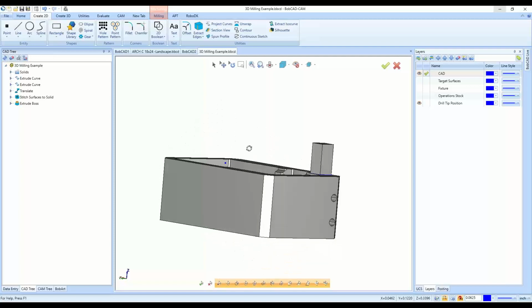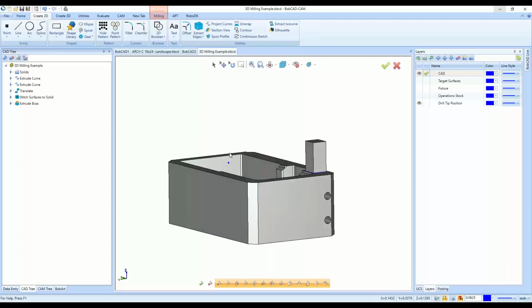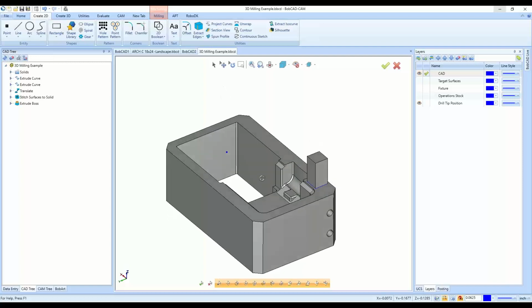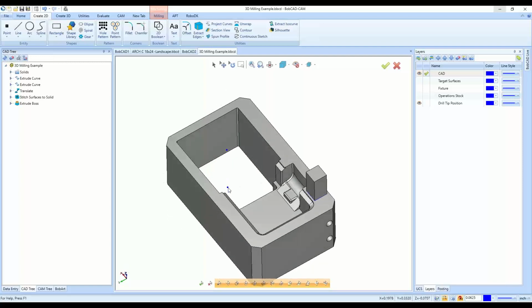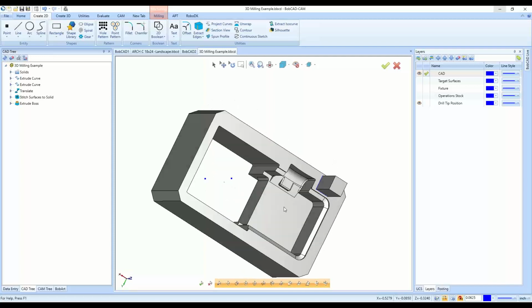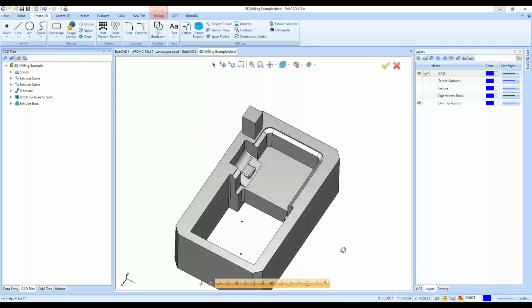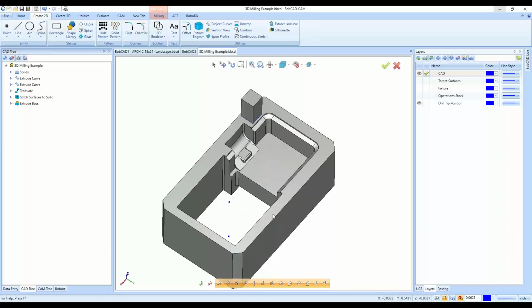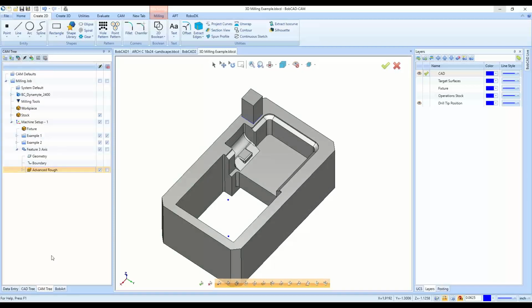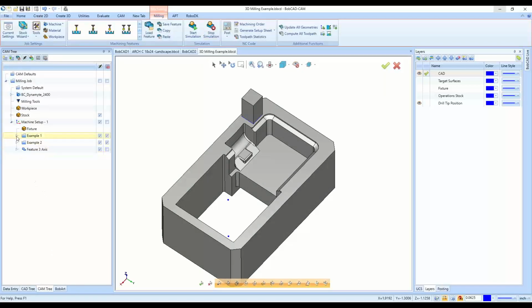You set it here at the Z0, it's just going to touch right there at Z0 and not do anything for you. You want it to go down here in 4 inches or however far that is, or however far you want it to go down to. If you don't want it to go down to the full depth, you can create a point in between these two depths to let the software know how far down exactly you want to go. And that's done here in example 1.